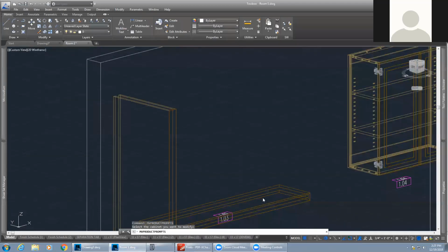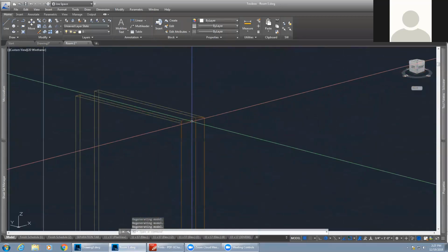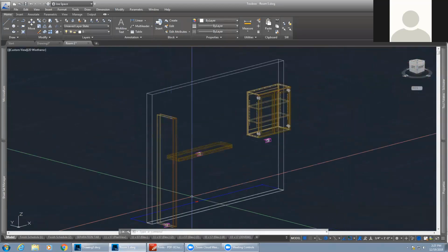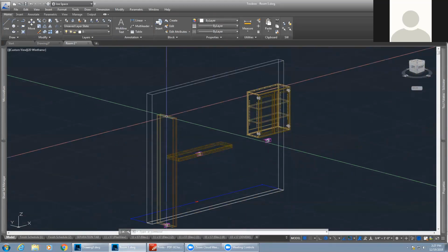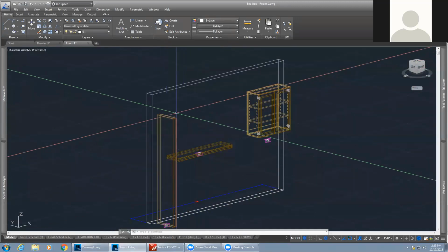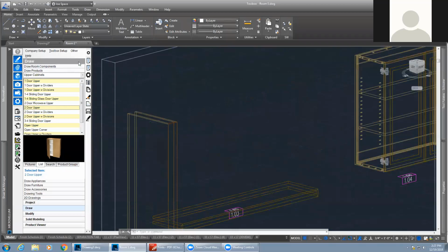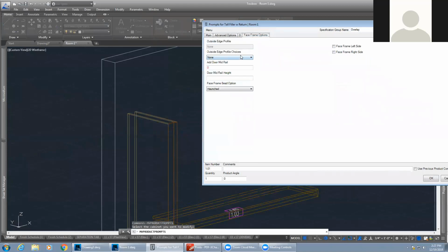So if I was just to change the size of that product into something different with a different hardwood nose, different plywood side, what's nice is that my 2D elevation changed with the correct dimensioning. And as soon as I processed this work order, all of the machining data changed, all on the same prompts. And then once you have a better understanding of the library data and how to develop it, more and more things become possible.